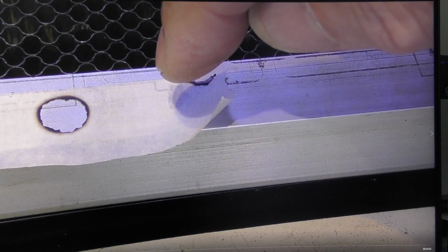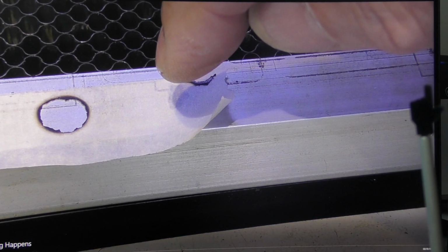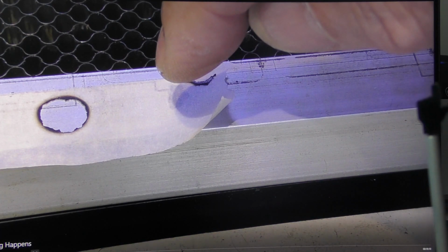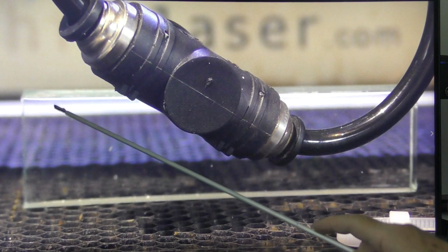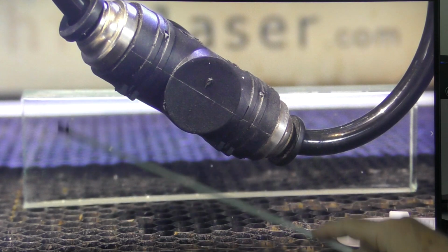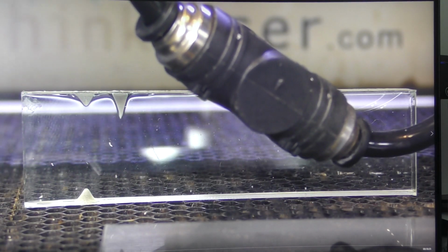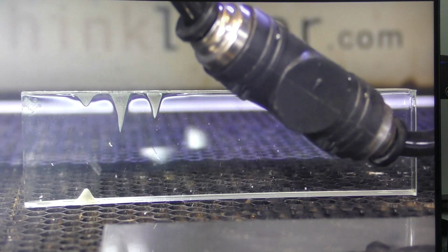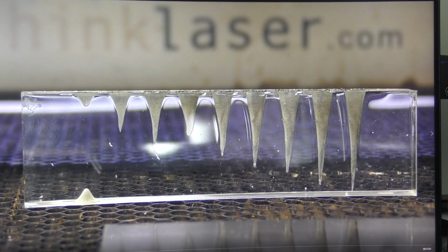Okay, now I'm going to step through little bits and pieces of a video that I made recently about the principle of cutting. That's the size of my beam when I leave it on for, say, 5 or 6 seconds. It will cut a 10mm hole. The manufacturer says that it's a 5mm beam. Here I've got a piece of 1 inch thick acrylic. And what you're seeing now is 1, 2, 3 seconds worth. So that's 9 seconds, and this is 10 seconds.